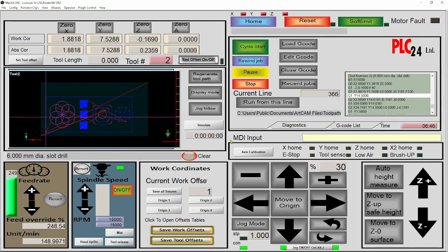And remember, the cut out is going to be 2 passes because the cutting depth is more than a step over. Cutting depth is almost half an inch. Step over is 0.25.